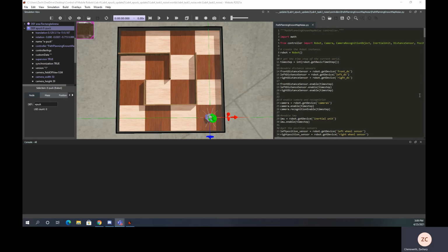In this task, we have to have our robot start in a starting location and end in a goal location. Then we have to use path planning algorithms to plan the shortest path to get from start to end. Just like my previous video, I'm going to use the wavefront algorithm. All this algorithm does is place a 2 in the goal location, and then count the possible spaces to get to the starting position, and the robot is going to take whatever path has the least amount of spaces.